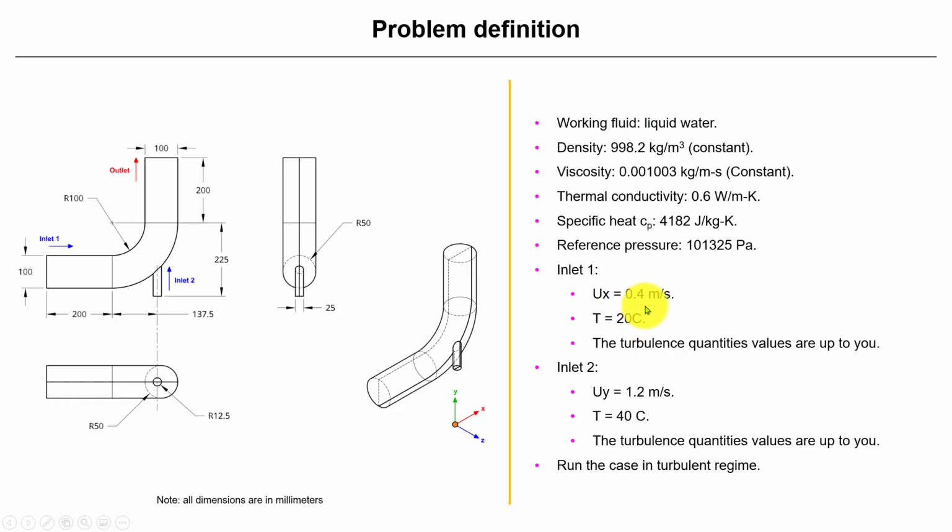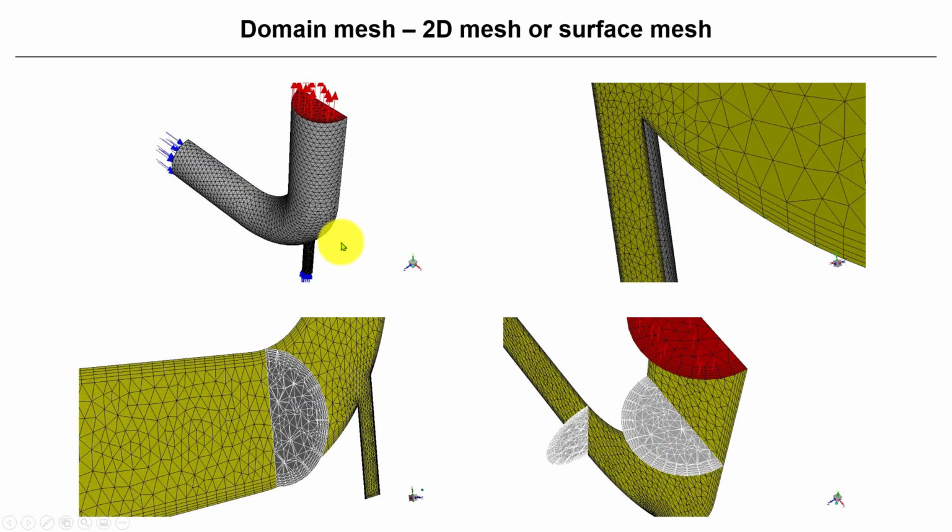Remember, I will enable again here the temperature equation, but if you prefer, you can enable the passive scalar. It's up to you, it will be the same. Okay, so this is what we have. We have this mesh. Okay, so see that in 3D, since they become bigger meshes, you are going to have a larger cell count. Now you need to pay a lot of attention to mesh quality, but see, still it is a nice mesh. Okay, we added our inflation layer, tetrahedral meshes.